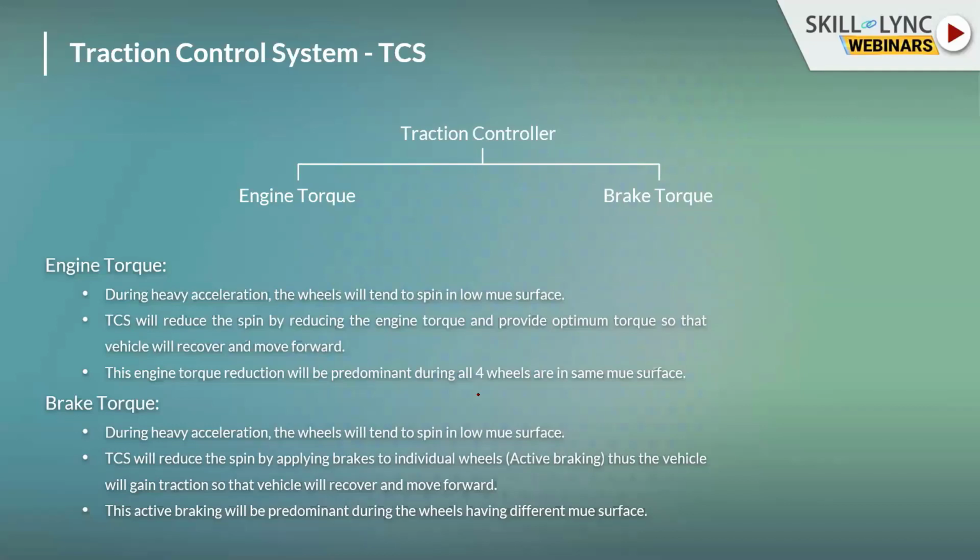If it is a combustion engine, it has a certain limit called the stall factor. Around 700 RPM is the stall RPM, and if you go below that, the combustion engine will shut down. For an electric motor, there is no such situation. We can go down to 0, and we can also increase up to 3000 or 4000 RPM, so there is much more room. But for a combustion engine, there isn't that much room. We can reduce the engine RPM only down to 700 RPM, so up to a certain limit we reduce the engine RPM on the ice surface.